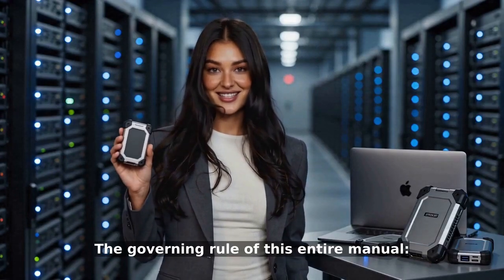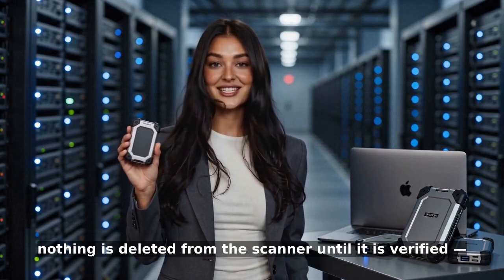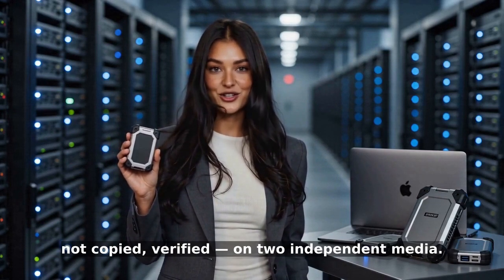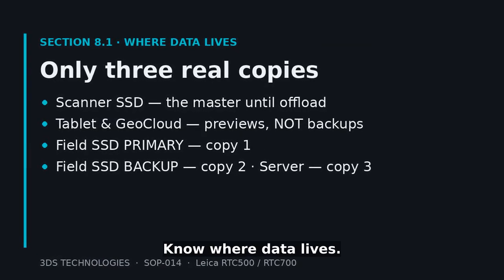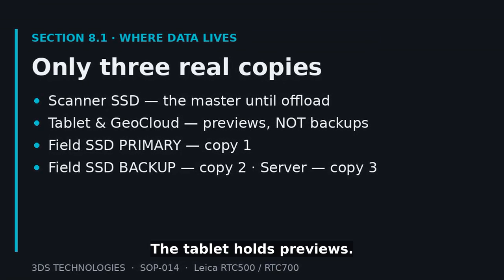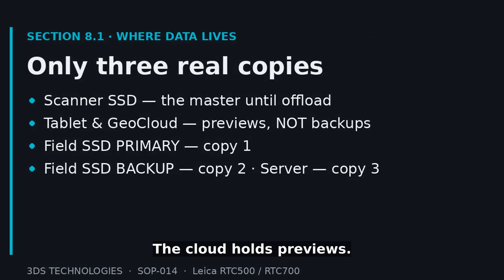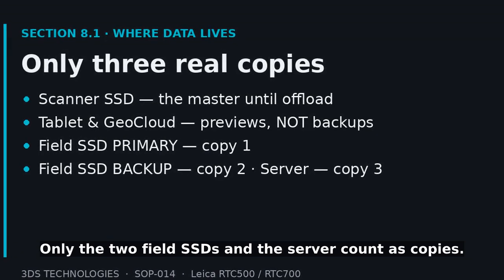Data custody. The governing rule of this entire manual: nothing is deleted from the scanner until it is verified, not copied, verified on two independent media. Know where data lives. The scanner holds the master copy. The tablet holds previews. The cloud holds previews. Only the two field SSDs and the server count as copies.